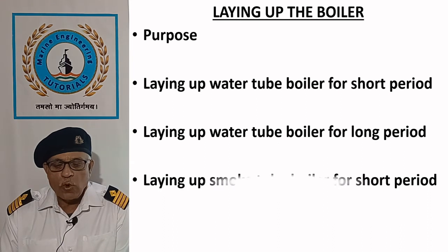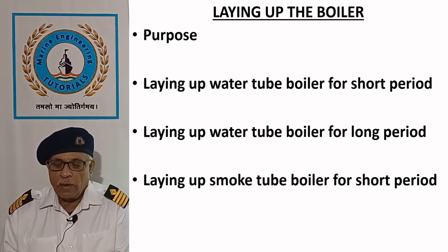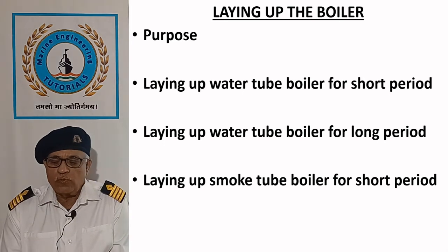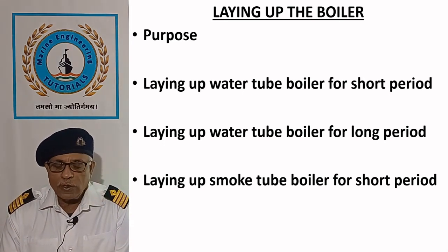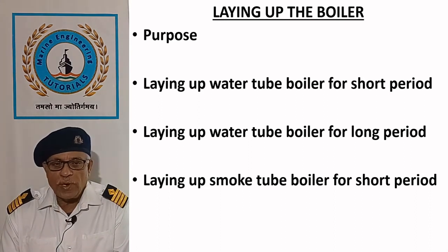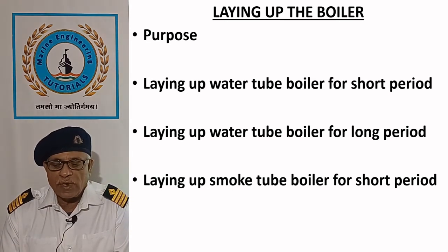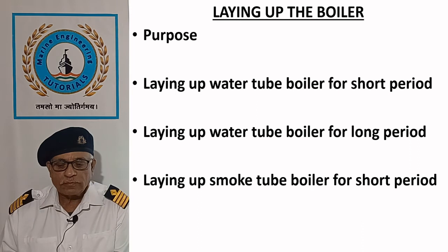Laying up smoke tube boiler for short period. While laying smoke tube boiler for short interval, only precaution required is either to maintain required phenolphthalein alkalinity or to fill up water completely with alkaline water.